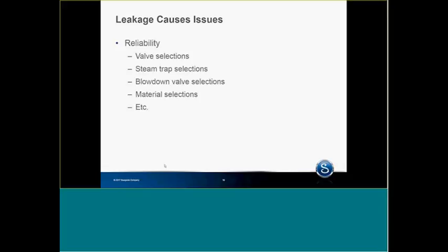We do have valves that we put in the steam system where the vendor has a lifetime warranty on the valve. Lifetime. And then we have valves that can go in the system to meet the code, and the warranty is when you take it out of the box. There is no warranty, okay? It's going to leak like a river. We should be getting somewhere around 30 years of operation out of a valve without any issues.